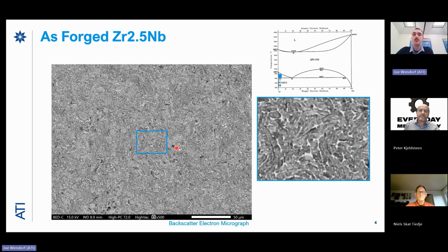That's part of why we forge it in this way. When you have a really large and coarse microstructure, certain grains will deform differently than others. That's true when it's a fine microstructure as well, but with a very coarse microstructure, that deformation is less homogeneous. Certain grains will deform more than others, and you'll see wrinkles and shear bands in your alloy that limit how much ductility the overall alloy has, because your ductility is concentrated into individual grains, whereas here we can distribute that deformation more evenly throughout the microstructure.